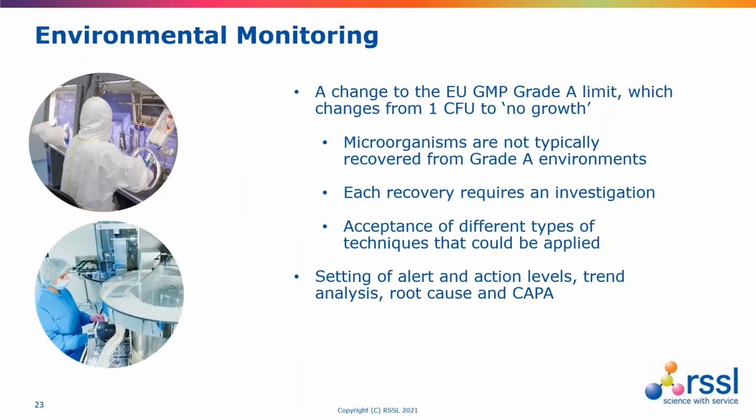It also appears that with environmental monitoring that the EU GMP grade A limit will change from 1 CFU to simply state no growth. And I think this change is a reflection of the expectation that microorganisms are not typically recovered from grade A environments.